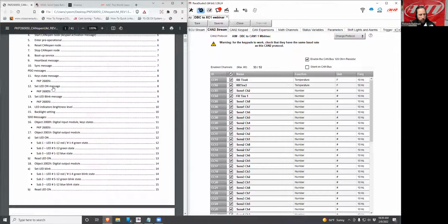So the keypad, all it tells me is that there is a momentary press of this button. It is the responsibility of the device, the PDM in our case, to send the LED state to the keypad, to also send the function of the button, whether it's a toggle, a multi-position, a locking, and then the respective colors for that. All of that requires a message to be sent to the keypad.